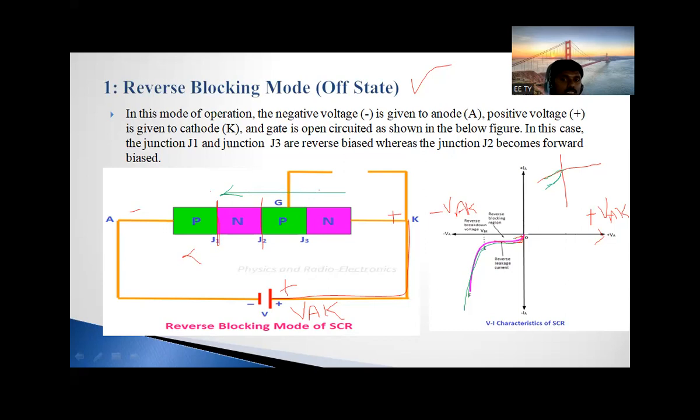But which current is this? Reverse current. This is the negative current IA. When the breakdown occurs, reverse current starts to flow from cathode to anode. It should not happen like that, because if it does, the thyristor will definitely get damaged. Is this point clear?